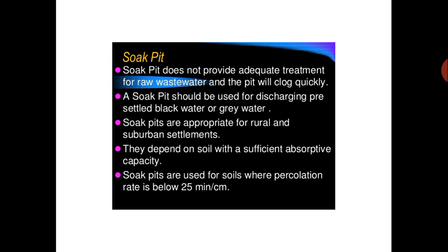Whatever wastewater is coming from the septic tank is directly introduced into the soak pit, where soil or gravel or some media will be introduced. The wastewater will come in contact with the soil. The soil should be able to absorb the dissolved organic matter present in the wastewater coming from the septic tank.